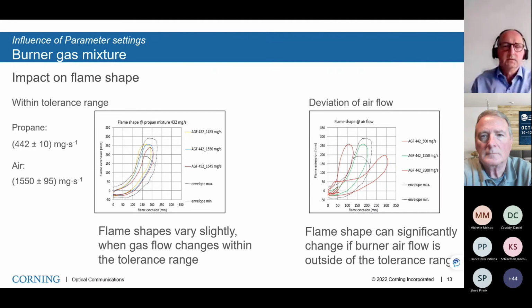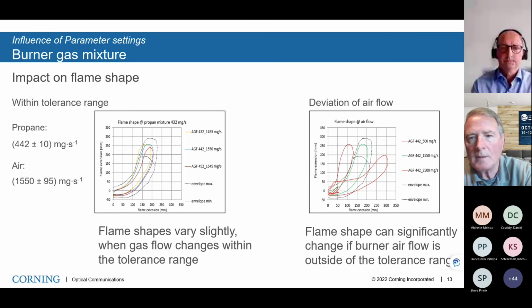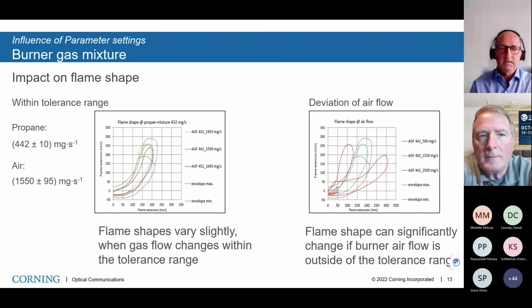You need to repeat the test with the cable design you want to understand, to get statistical evidence about the scattering of data, for example for the flame spread. So when we have an understanding with the reference cable, we cannot say it is the same variance in any other cable design. This needs to be investigated carefully.